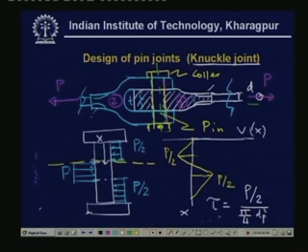So this is the shear stress developed. Now, we know from the basic theory of Euler beam that the exact distribution of shear stress is not the average, but the maximum shear stress occurs on the neutral plane, and for a rectangular bar it is roughly about 1.5 times the average value.